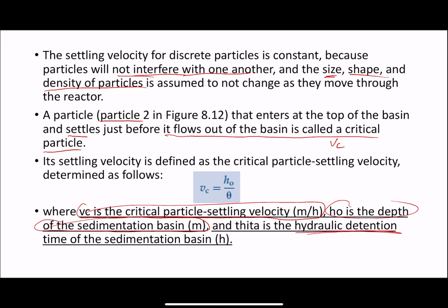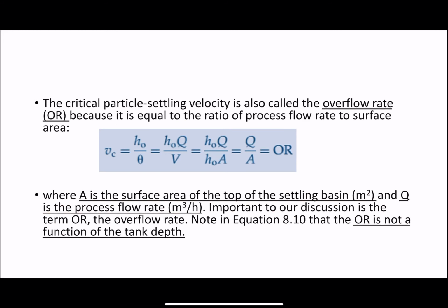Sedimentation time. Detention time. Sometimes they call it HDT, hydraulic detention time. So, the critical particle settling velocity, sometimes they call it overflow rate, and that's good for the design. Once we come and design tanks and design reactors, we need to check OR. OR is the overflow rate.